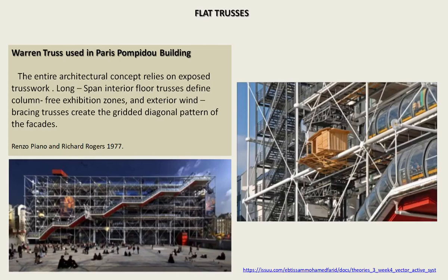And the wire truss used in the Paris Pompidou building. The entire architectural concept relies on exposed truss work. Long span interior floor trusses define column-free exhibition zones and exterior wind bracing trusses create the graded diagonal pattern of the facades.